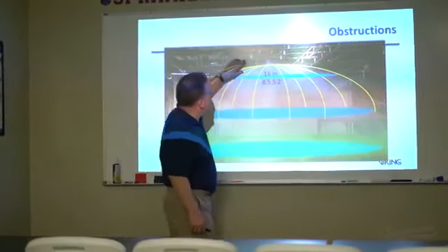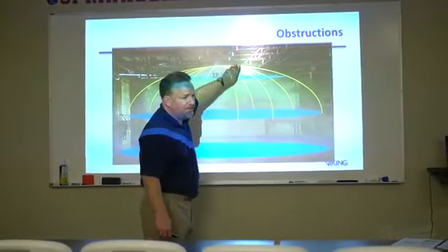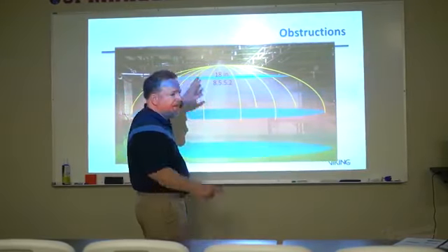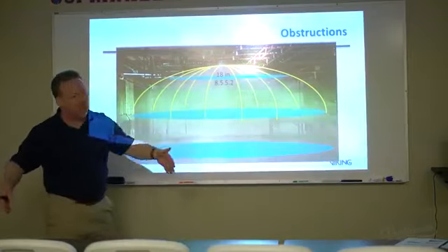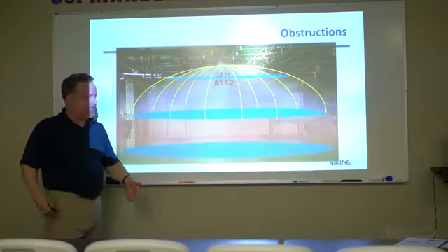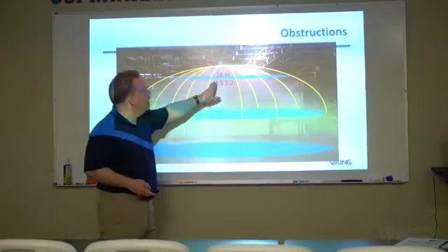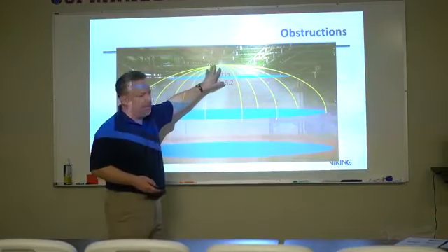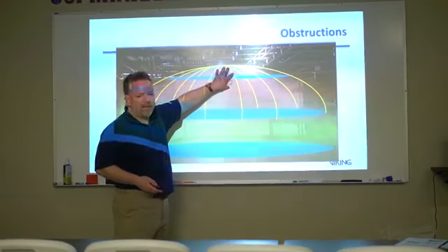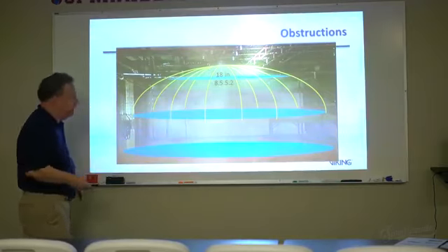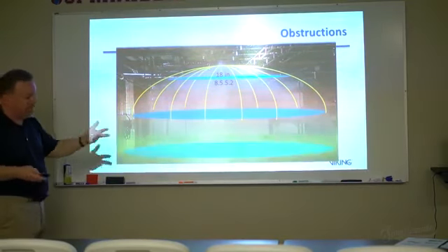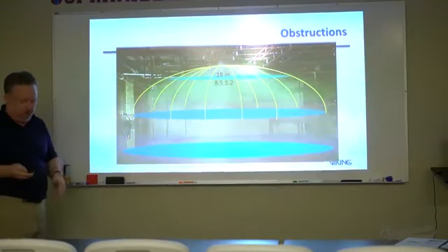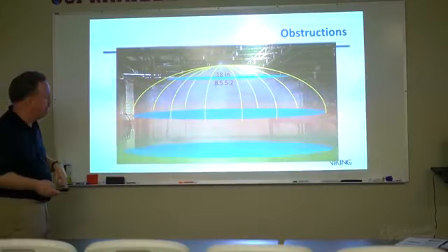In other words, any obstruction, beam, light fixture, anything up in this space is going to obstruct the spray pattern from even developing. So 8.5.5.2 says that you're going to have to pay attention to these. Not that they're not going to exist, but we have some specific rules on obstructions to spray pattern development.